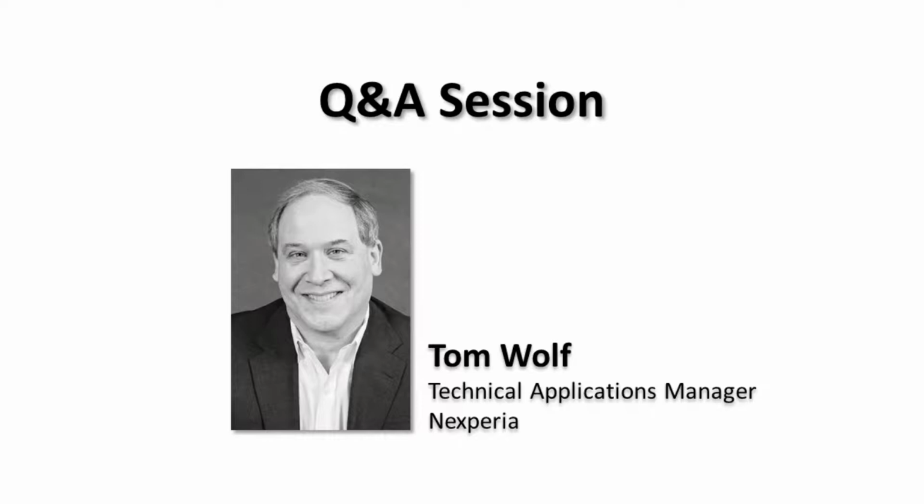When Nexperia designs the part, we actually use different silicon processing techniques to get the lowest RDS(on) that we can, but also keep that charge down, keep the capacitance of the device as low as physically possible. We're using trench technology and some passivation and a number of techniques to get that down. But you're right, you need to be aware of that. The lower the RDS(on), check the capacitance of the part itself. It's in the data sheet, and make sure you compensate for that.